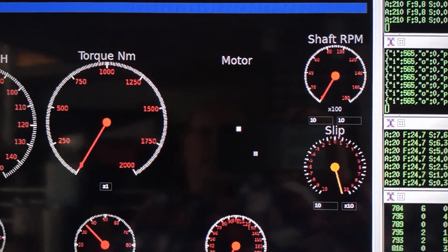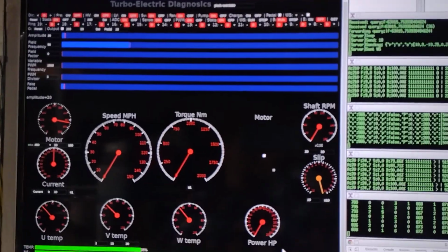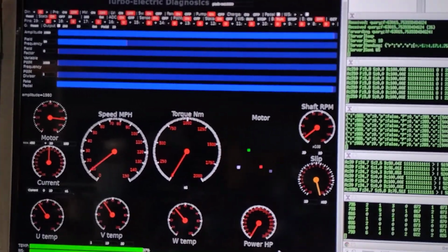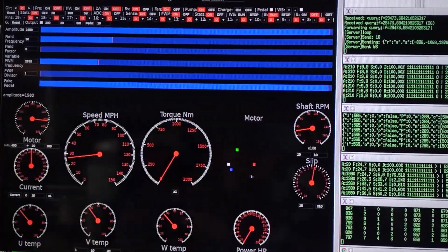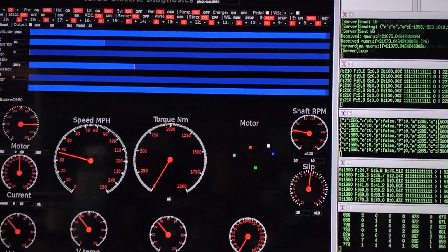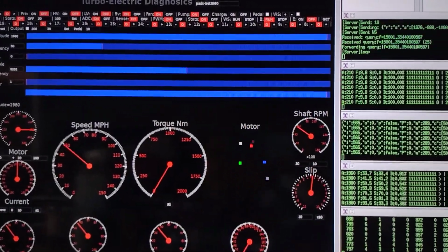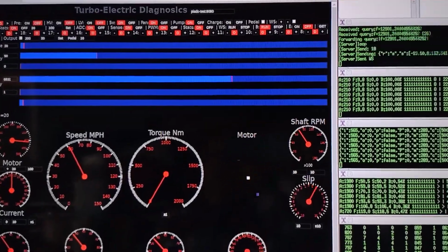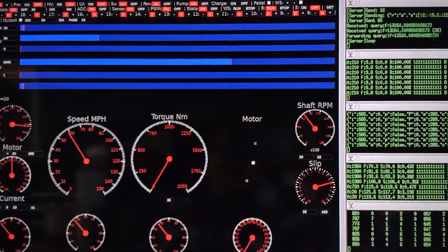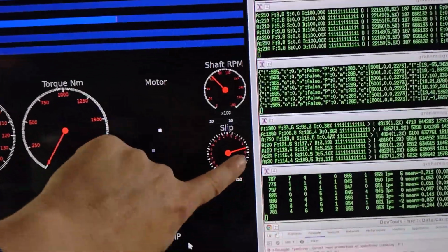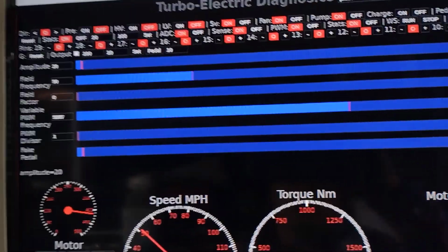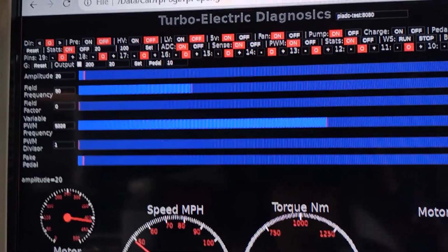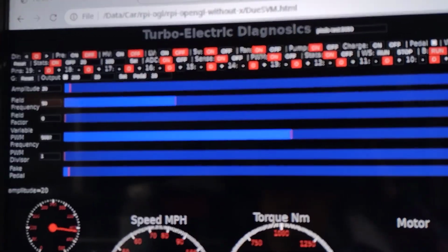This is just unreliable, the interface is unreliable, but it works right now. So stomp. There you go. Now do you see the slip go straight up, and now there's the VFD going up and accelerating it, and I'll stop it at 60. There we go. I just lifted off at 60. Now you can see that the slip's been held at 5% and the VFD is dropping. The frequency is dropping in the stator.